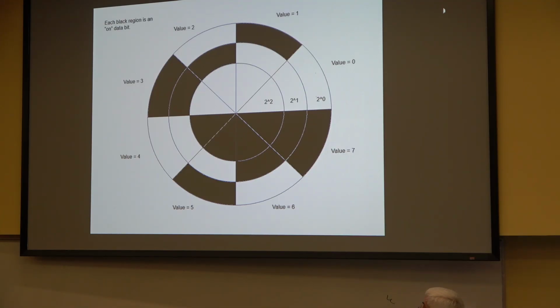And instead of actually cutting binary numbers into our encoder wheel, what we're going to do is use something called gray code. Guys, gray code, I looked and looked for a really good, easy way to describe this. But just think of it as binary numbers, same number of ones and zeros for any given number, but the key difference is that only 1 bit changes from number to number.